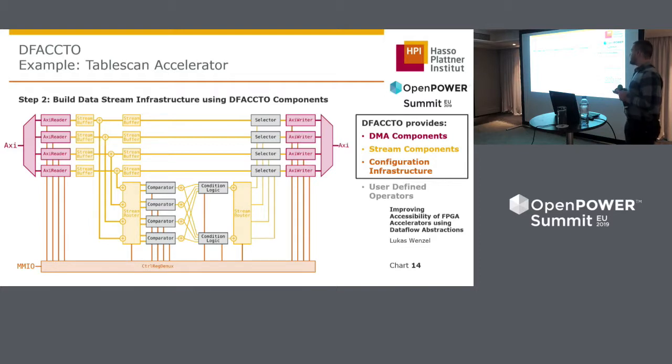They are important because, as you see, the pipeline length of this half of the design is not the same as this half. And as those streams are synchronous, we would actually block up the entire design while comparisons are performed here. Because those stream splitter blocks require both output streams to process the data or accept the data until they allow the next item to be presented.